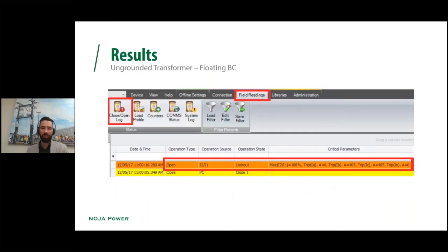So when we go to work it out, we sub those in, we run the simulation. Of course, I2 and I1 comes back as 100%, which again aligns with the topology that we defined before, where we said that if it's ungrounded and you have the floating broken conductor, I2 and I1 are equal. Therefore, I2 on I1 is 100%.